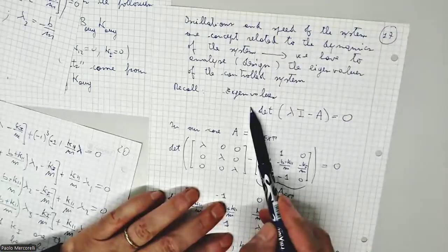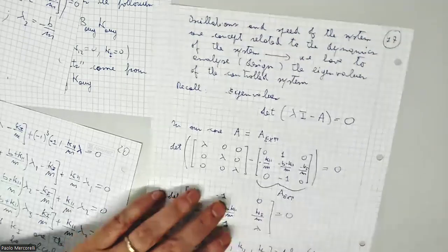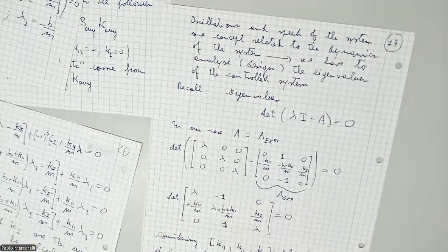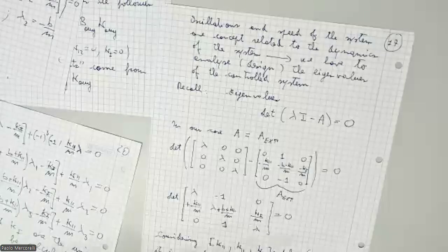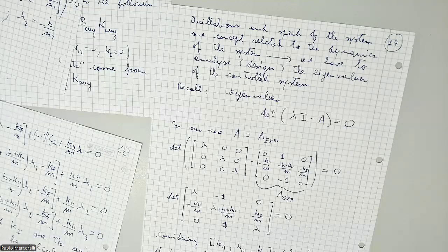Where this comes from again, from math, and then how lambda characterizes the dynamics of the system, the original system, but also the control system. In one case, I have to calculate lambda. In another case, for decided lambda, I calculate the parameters of the controller which realize our specification. In terms of no oscillations, this means no imaginary part of lambda.